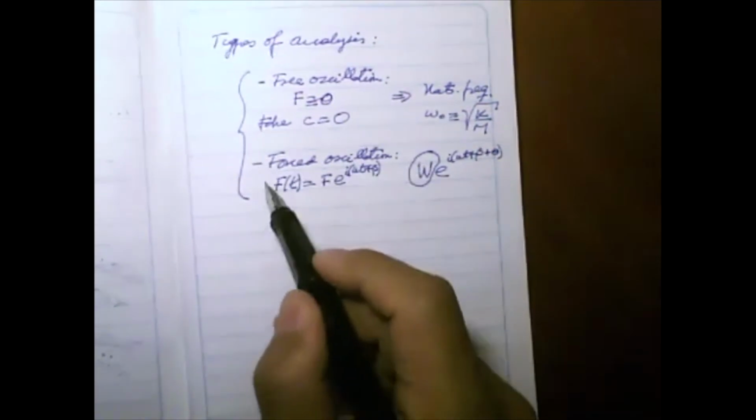Okay? Now, what else? In the case of the forced response, remember, we drew, or we were able to calculate, the amplitude W, this W, and here in the abscissa, we present the ratio between the excitation frequency and the natural frequency, okay? And when we are at a value of about 1, that means that these two are the same, the response of the system will increase.